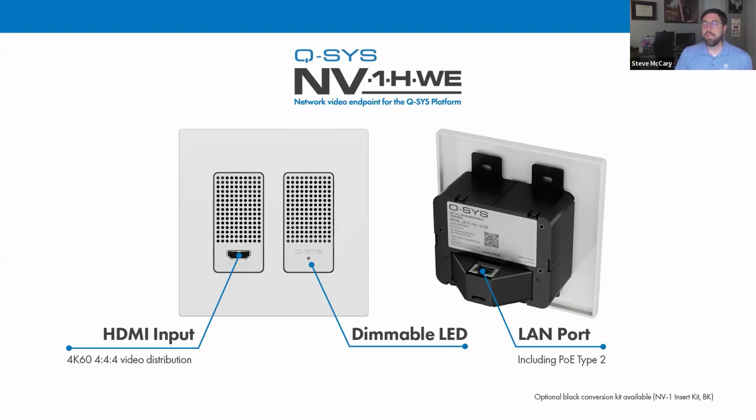So these take PoE type 2, so that is 30 watts. So that is PoE plus. They are single network port, so that is your LAN and your PoE and everything else that you need.